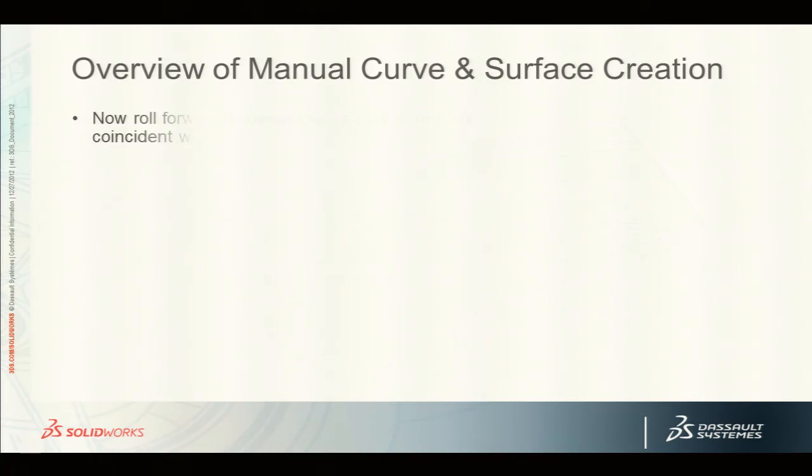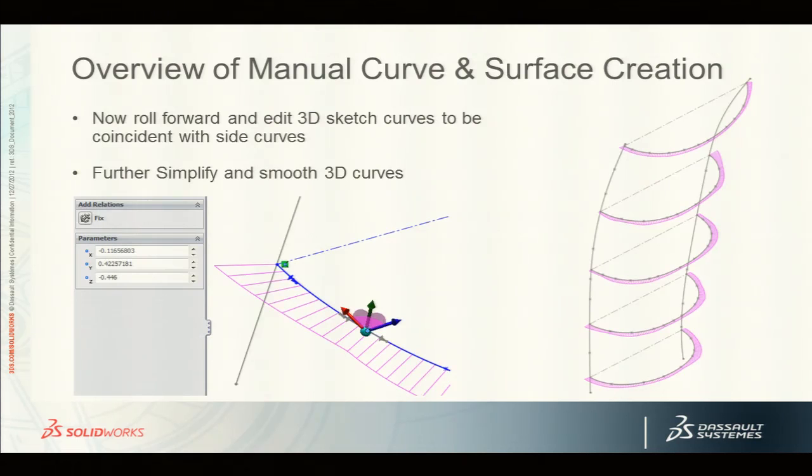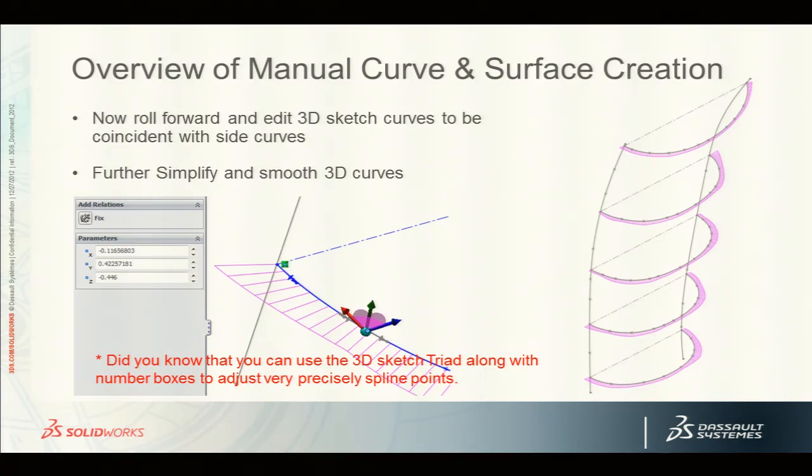I roll forward, and now I tie together those curve wizard curves with those second direction curves, because they have to be tied together, and that's what I'm doing here. In the image on the very right, you can see I've taken each of these curves and cleaned them up. I've also connected them either with a pierce or a 3D constraint to those rails that I created just before by rolling back. So now I've got everything I need to create my 3D boundary surface.